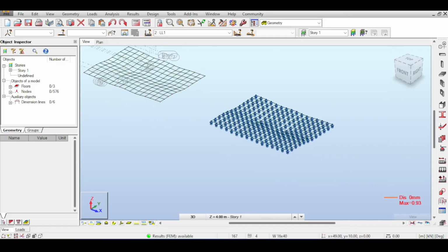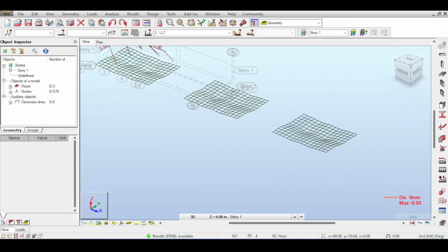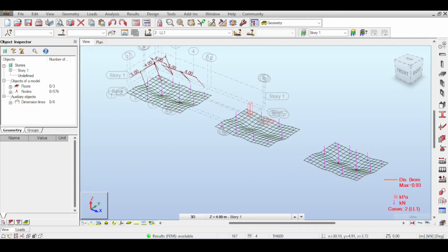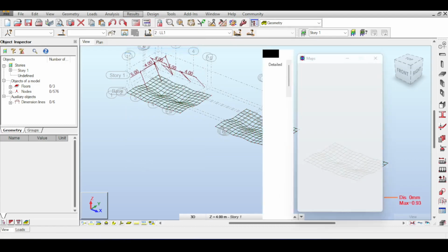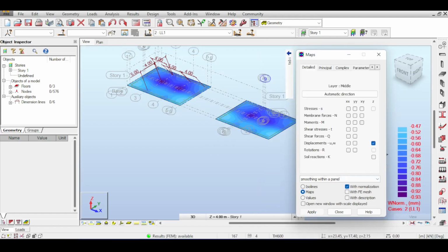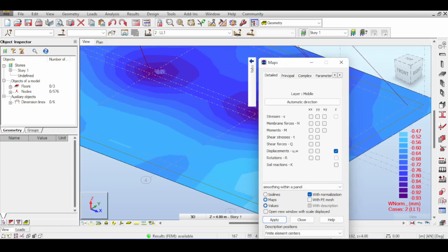So I'm not really sure if it works or not. I'm still skeptic. Now, of course, I will not take a look on this one because here I have added my improved loads. I have to compare apples with apples, so I'll compare this with this. And I think, technically speaking, they seem to be the same. I'm getting happier as I'm talking, but I need to make sure, of course. So I go to maps, results, maps, and I'll select the deflection in the Z direction, just make sure. And let's take a look. So I'll just go there and select value and just stand here.